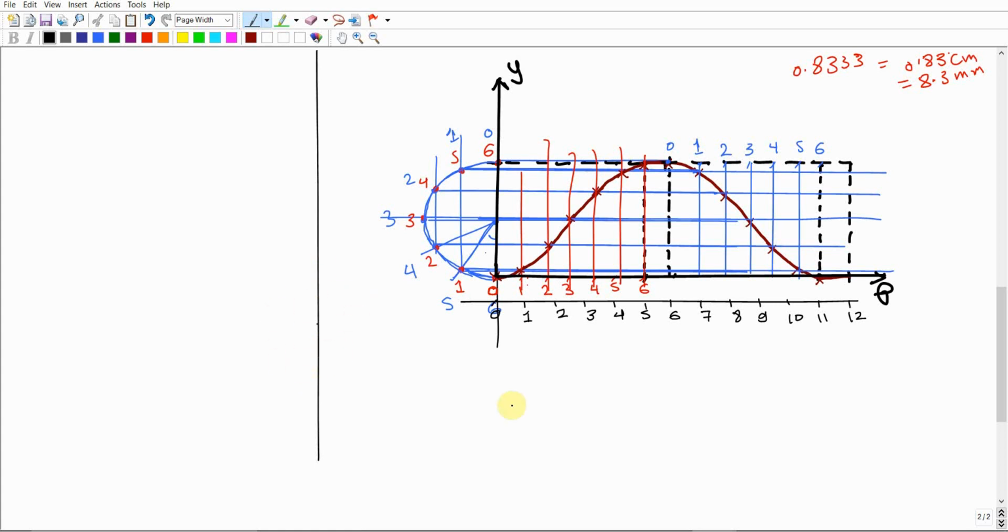So the first step is just to draw this horizontal line and break it into 12 centimeters, and this vertical line. Then your objective is just to start to draw vertical lines from every one of these marks over the new horizontal line. You're just gonna go up, intersect with the displacement diagram, then go horizontal and put a mark next to this mark 1. For mark 1, I'm just gonna draw a vertical line till I intersect with the displacement curve.